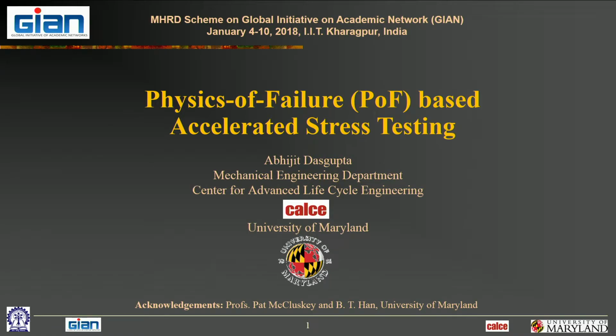Number one. Number two, sometimes you're worried whether you accelerated the test a little too much because you were in a rush. So people will usually run longer-term accelerated tests even after the product's been shipped, just to see if for the second generation or third generation release, you need some minor tweaks in the product. And there's always ongoing changes in materials. There's always cost-saving moves, and materials get changed in your design. So there are ongoing reliability tests to see how good those materials are. Okay? So there are several points in the life cycle where accelerated stress testing is conducted.